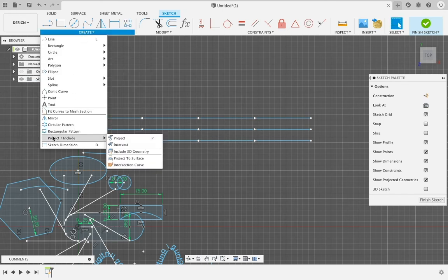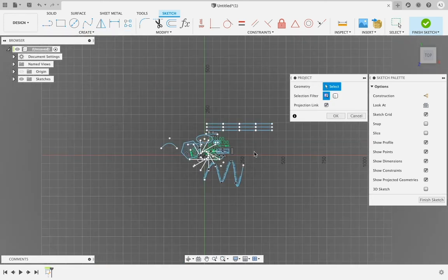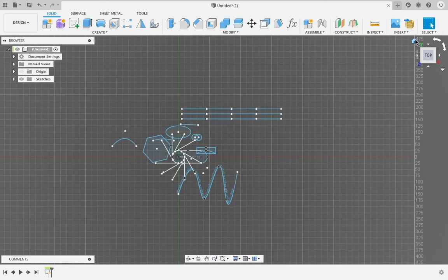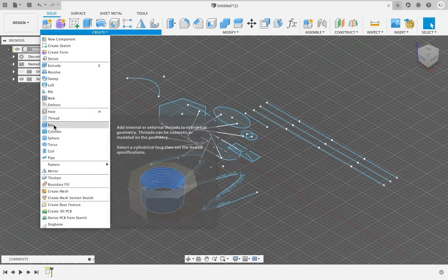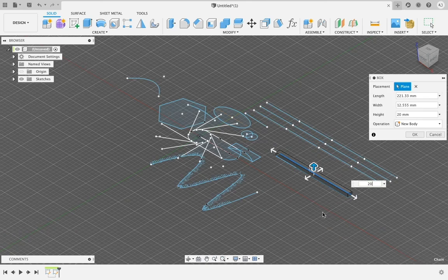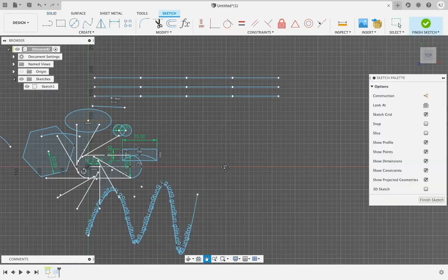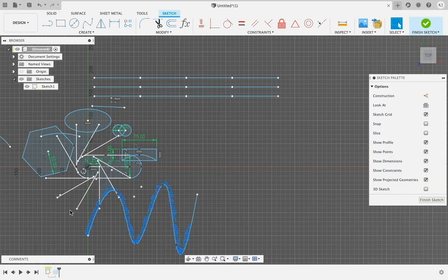Next, we can use the projection or intersection piece. The projection tool is very useful, and I will set up an example. If I take a standard cube and I place it across the plane, I'm going to create a random one, and I'm going to enter back into the sketch by opening the sketches folder and double clicking this to edit it. Unfortunately, the cube will not show, but that is okay.